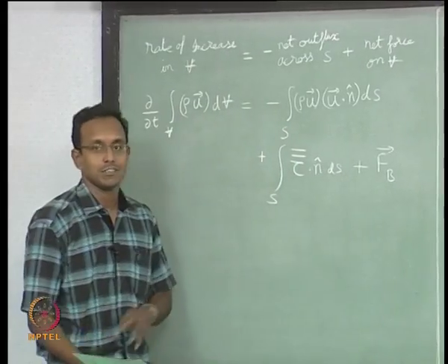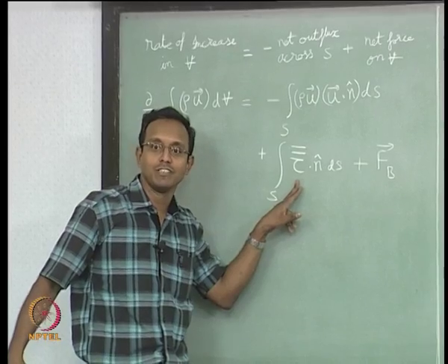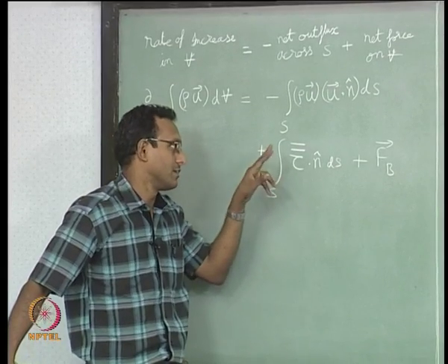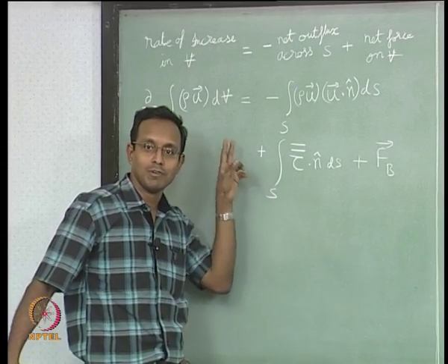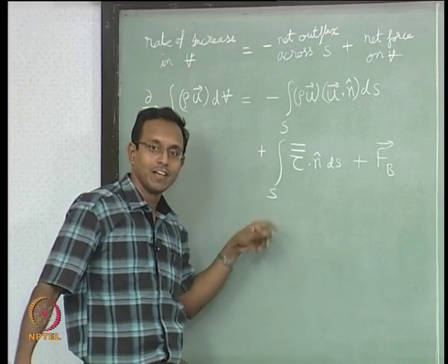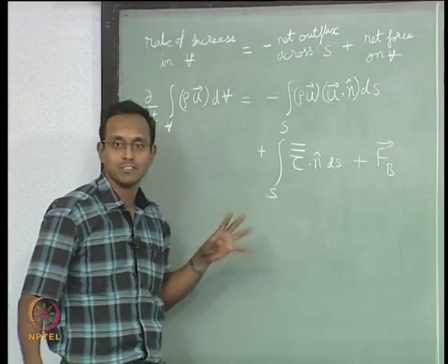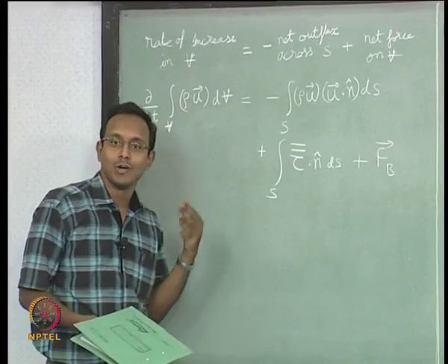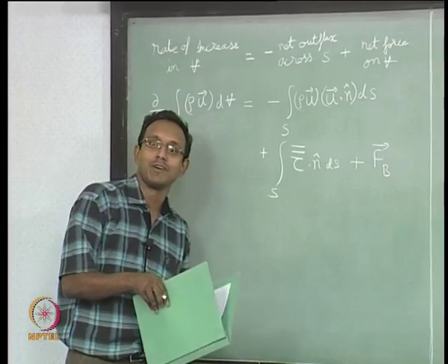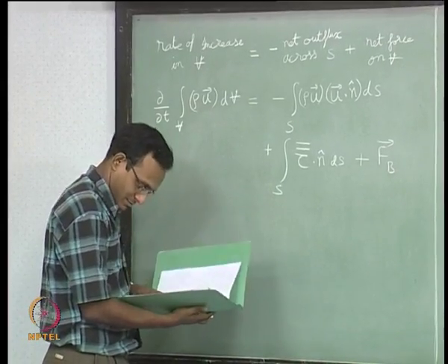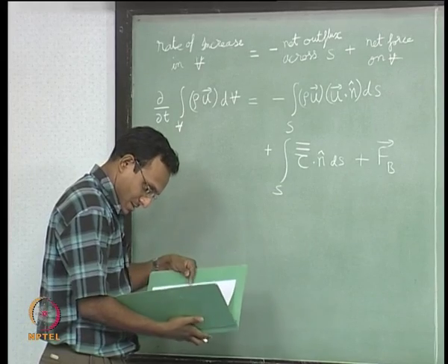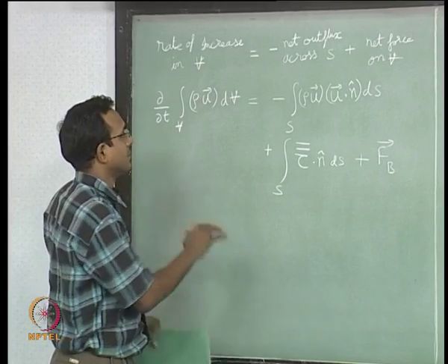The stress tensor is the full matrix form, the 3 by 3 form, and along the diagonal it will include the normal force components, and the off diagonal terms will be your shear stress terms, right. You know, tau x y, the most common one used in Newton's law of viscosity. Okay. So, this is the full equation.